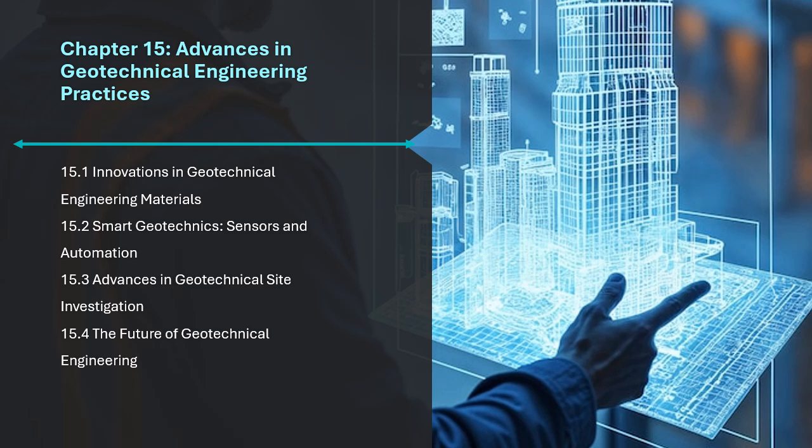Borehole acoustic logging. Borehole acoustic logging involves the use of sound waves to evaluate the properties of materials within a borehole. This method can be used to measure parameters such as soil stiffness, porosity, and permeability. Applications: borehole stability analysis, identifying soil layering, and determining the stiffness of materials. Advantages: provides high-resolution, continuous data that is useful for understanding soil behavior in situ.